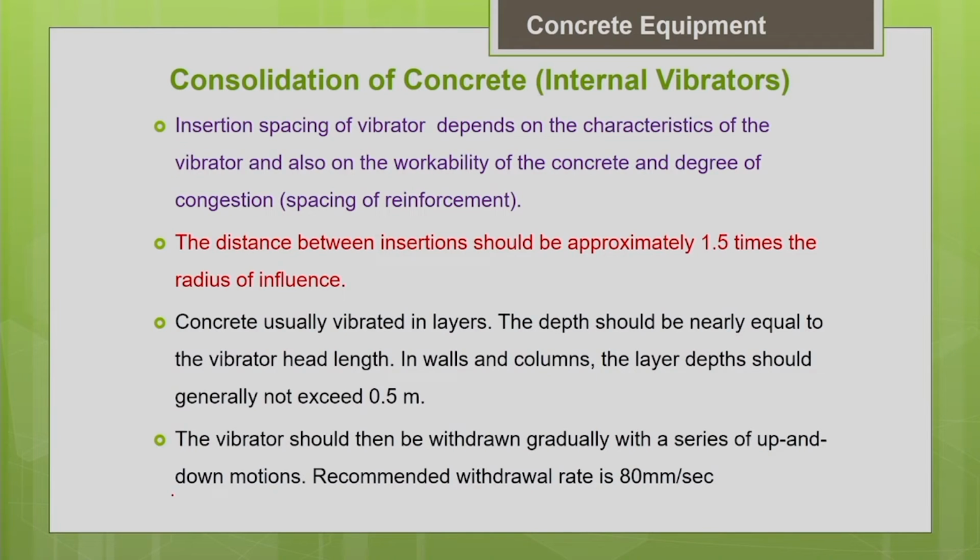If the worker who is doing the vibrating job feels that the concrete is very stiff, he will reduce the interval of spacing. When he feels that the concrete has better consistency, then he will increase the interval of spacing between the vibrators. That is how it is commonly done at the job site, just based on experience by looking at the concrete consistency.